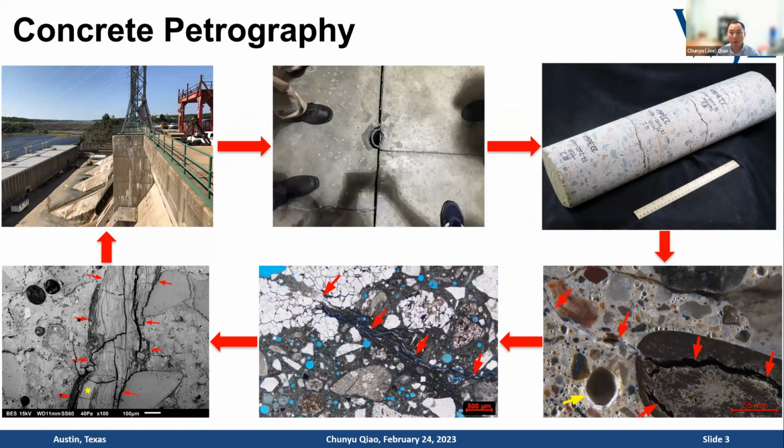will notice some problem. For example, this is a hydraulic dam somewhere in Canada. You can see in the exterior survey and within the structure of this dam that there are very extensive cracks everywhere, and you see a lot of white exudation oozing out from those cracks. Along with those cracks, we see a lot of steel reinforcement corrosion, and a lot of concrete cover falling. This whole structure is in very severe condition that requires a lot of attention, repair, and maintenance.